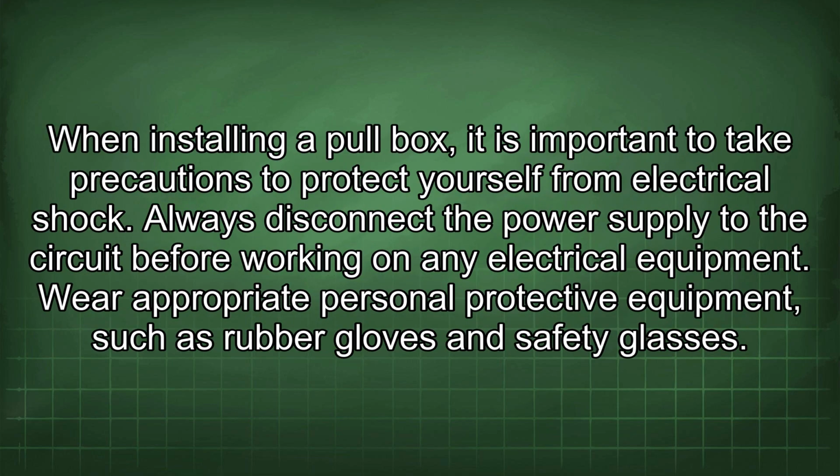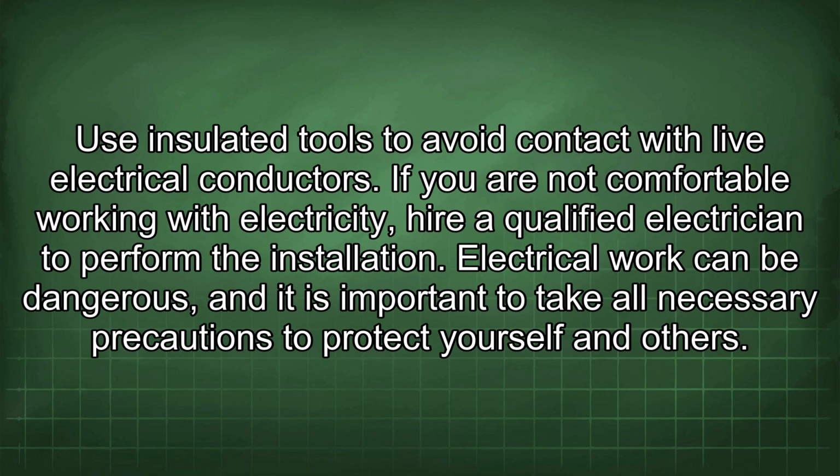When installing a pull box, it is important to take precautions to protect yourself from electrical shock. Always disconnect the power supply to the circuit before working on any electrical equipment. Wear appropriate personal protective equipment, such as rubber gloves and safety glasses. Use insulated tools to avoid contact with live electrical conductors. If you are not comfortable working with electricity, hire a qualified electrician to perform the installation. Electrical work can be dangerous, and it is important to take all necessary precautions to protect yourself and others.